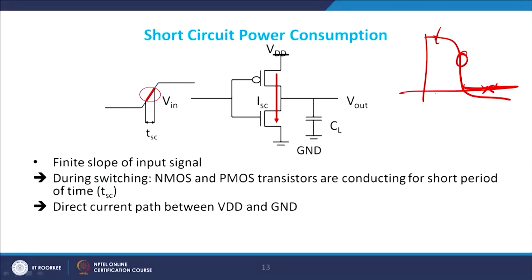Somewhere here in the middle, where you have the switching threshold approximately equal to VDD by 2, your NMOS and PMOS, this is your PMOS and this is NMOS, are equally on, getting my point, which means that both the transistors will be able to pull the charge carriers from the peripheral onto the capacitive load, fine. So, that is the reason the short circuit power dissipation is very low in case of a simple CMOS inverter, and this is an interesting idea.